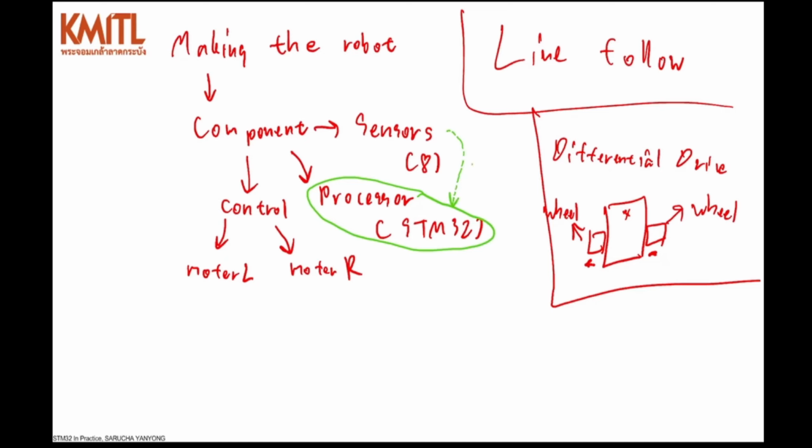The way we get the information from the sensor is ADC and DMA. ADC and DMA get the analog value and keep it in the DMA because it's very fast, and then we read it into the processor. Do you remember we normalize the values to get the position of the robot compared with the line?